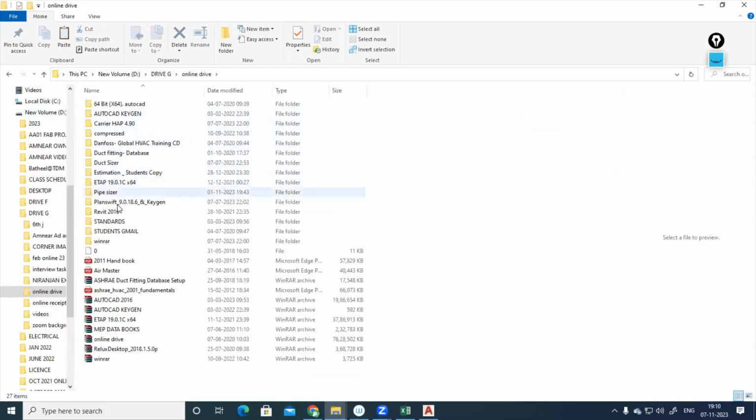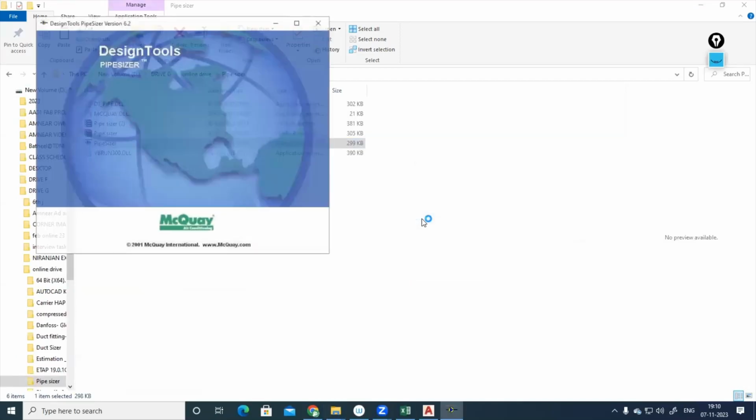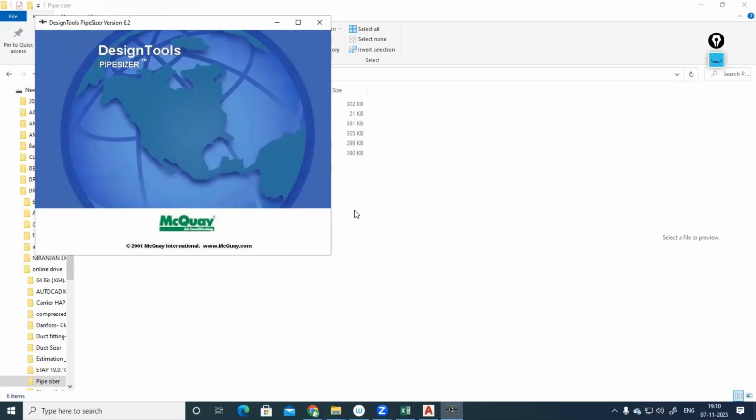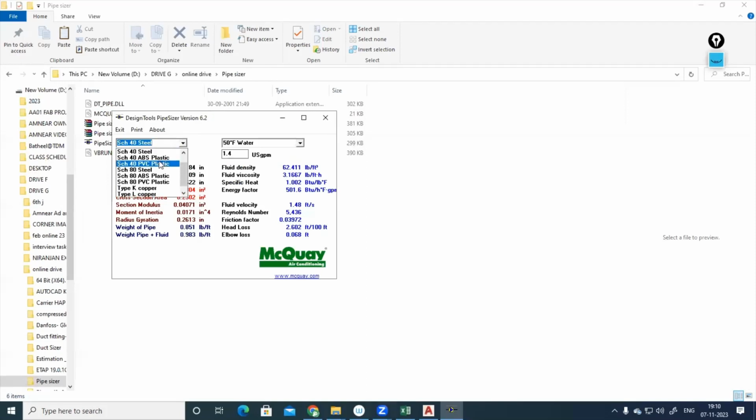Pipe sizer, let me select it. Water supply only, so I'll be selecting schedule 40 PVC plastic. Water temperature 70 degrees Fahrenheit. Okay, what diameter do we need?